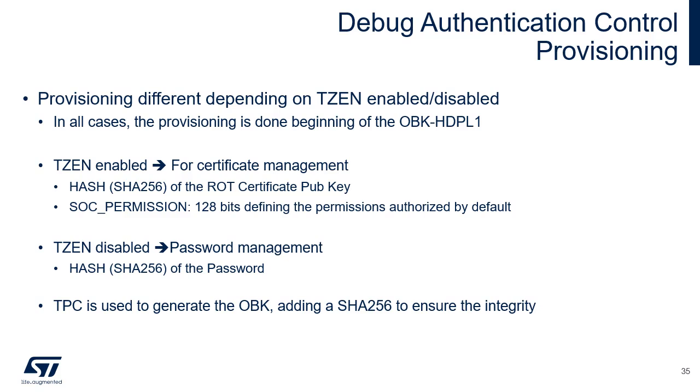A tool designed by STMicroelectronics called Trusted Package Creator or TPC is used to generate the OBK, adding a SHA-256 to ensure the integrity of the stored information. TPC is part of the STM32Cube programmer toolset.